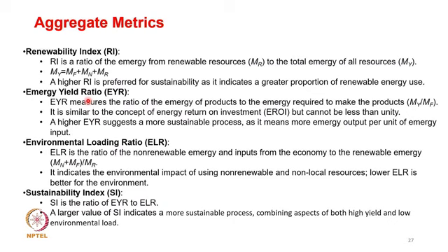The next is the emergy yield ratio. So EYR measures the ratio of emergy of the product to the emergy required to make that product, which is My by Mf. Okay, it is similar to the concept of energy return on investment, but cannot be less than unity in this case. The higher EYR suggests a more sustainable process, which essentially means that more energy output per unit of energy is given as input.